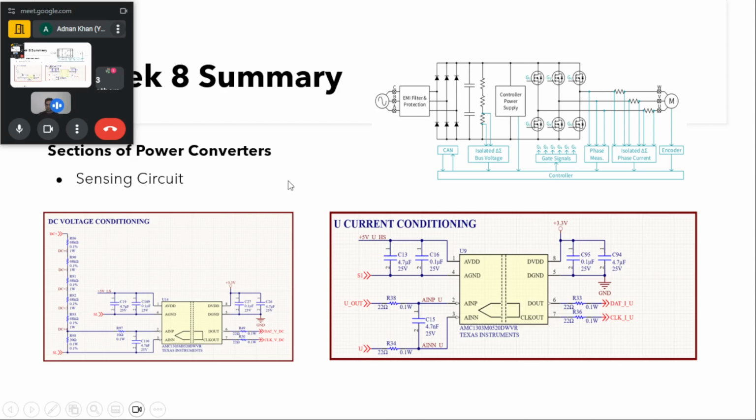There are a number of ways to sense this voltage, and one such way is like this, by using a resistor divider. Here you can see in the voltage sensor, we'll be having a resistive divider circuit, where we'll be giving the whole DC for this DC voltage sensing, and then we'll be using some resistive divider, and across one of the resistors, we'll be taking the output,